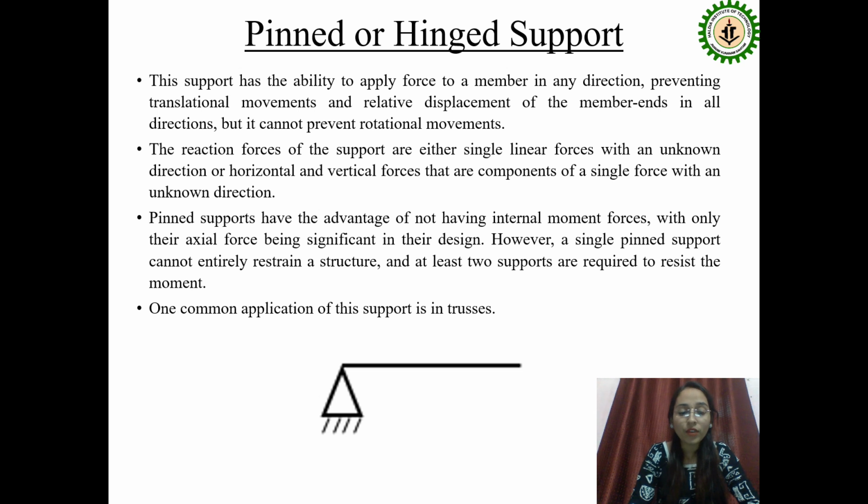So here, where will be the reaction forces? As the horizontal movement and vertical movement are restrained, therefore reaction forces will be on those two sides, that is in the horizontal direction and in the vertical direction. So for pinned support, reaction will be vertical and horizontal, and degree of freedom will be only in the rotational part. Okay. It is also commonly seen in the trusses.